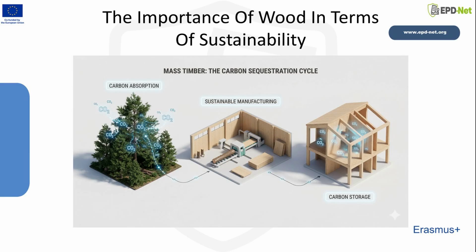Modern engineered wood products expand the possibilities of timber architecture by improving dimensional stability, structural performance, and predictability. From a spatial perspective, wood contributes warmth, texture, and natural variation to architectural environments. However, these benefits depend on correct design decisions. Poor detailing can lead to moisture damage, decay, deformation, or reduced durability. Therefore, wood should be evaluated as a performance-based architectural material.